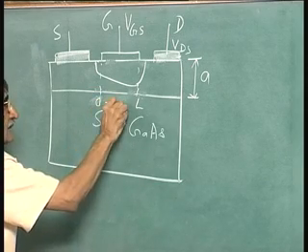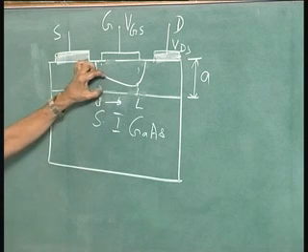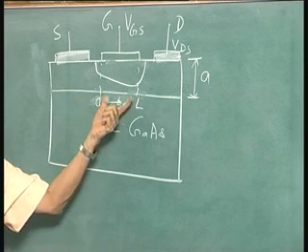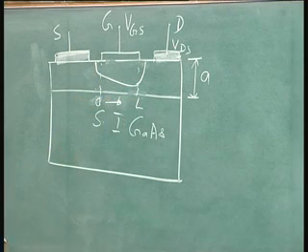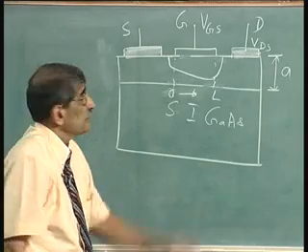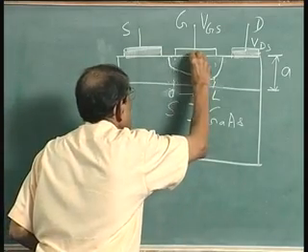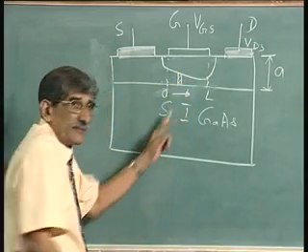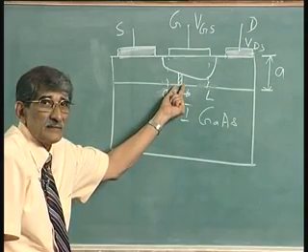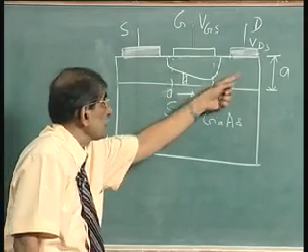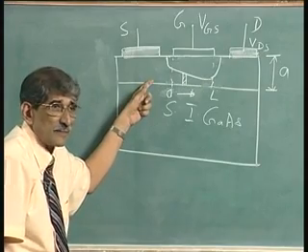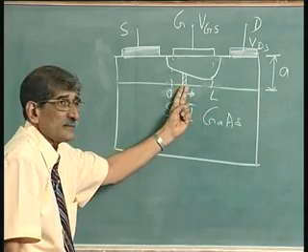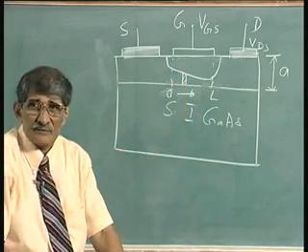So, what we are telling is, we have to find out the voltage drop across this region and relate it to the current. Same law, Ohm's law, V is equal to I into R. We have to find out the resistance. So, what we do is, take a strip here of width dx, find out what is the drop across that due to current I_D, because current is constant right through, there is no current accumulation. So, find out the drop I_D into rho dx divided by area of cross section, that is all what you are doing.